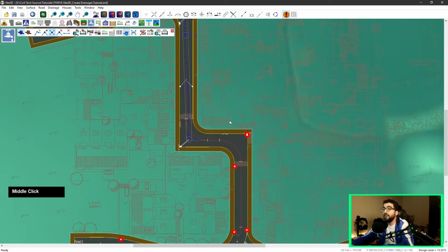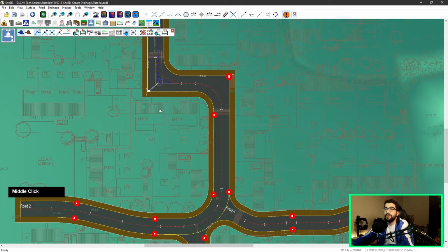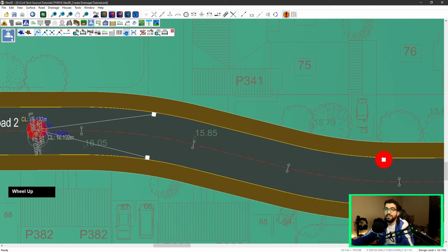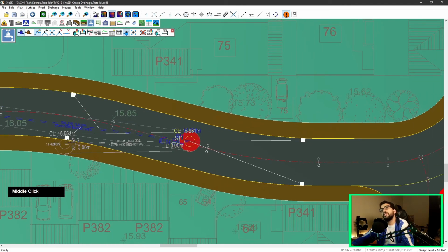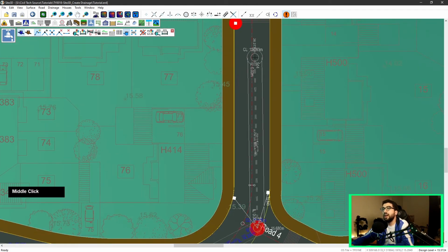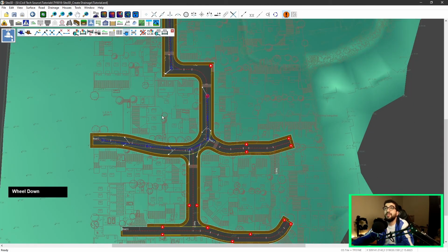So let's say here we don't have any run, right? If we add a new run, let's say here, see, it picked up the gullies, and if we put it here, it changes the direction of the gullies because it's smart, let's put it this way, and it picks it up. So this is by far my favorite command inside 3D. Then we've got the move manhole annotation.